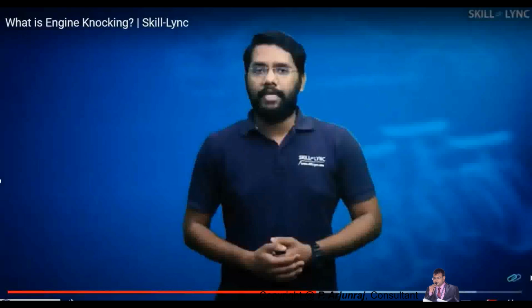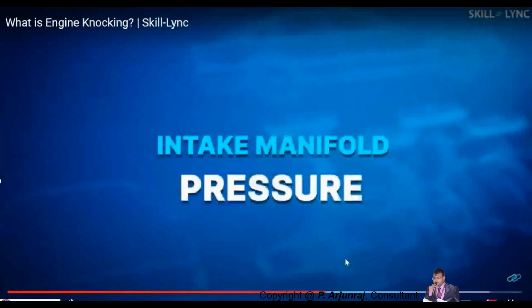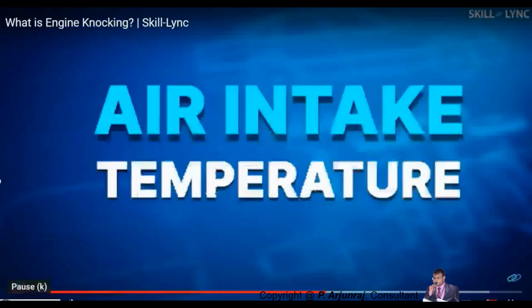So the compression ratio maximum comes to 10.5 to 1 or 11, maximum 11 or 11.5. Beyond that, in the case of a gasoline engine, you get a knocking sound or a knocking phenomenon. So when you reduce the compression ratio, you can also reduce the knocking. And when you reduce the pressure, the temperature is going to be lower, and the peak temperature is also going to be lower. That will also reduce knocking.